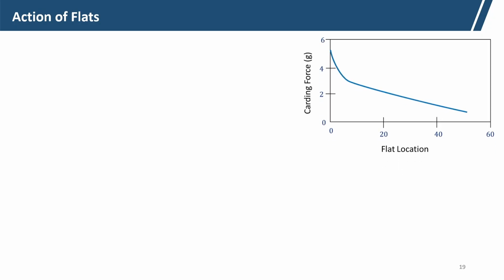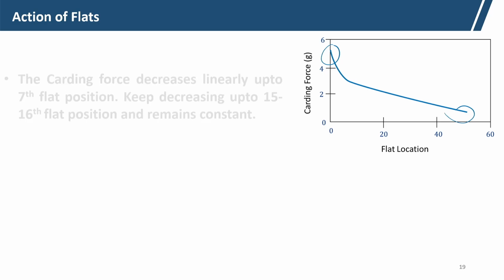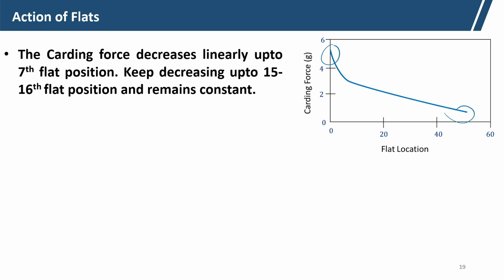Now, regarding the action of flats, you can see the flat location. The carding force is maximum at the beginning, and it reduces up to, say, the 7th flat. There is a sharp decrease, and it keeps decreasing up to the 15th flat, and then it flattens and remains constant.